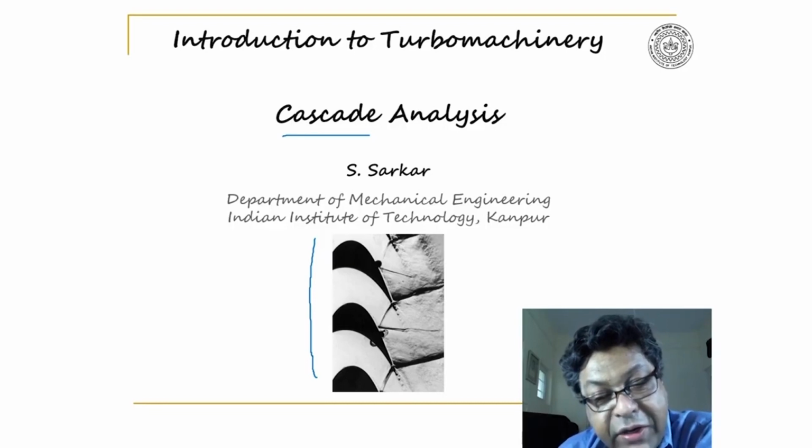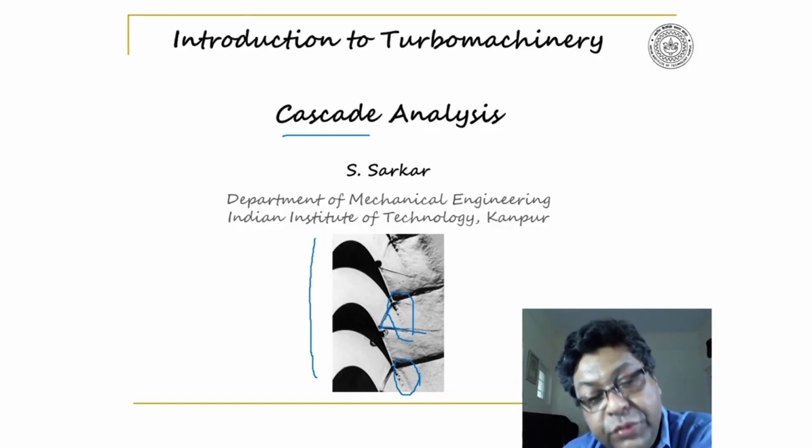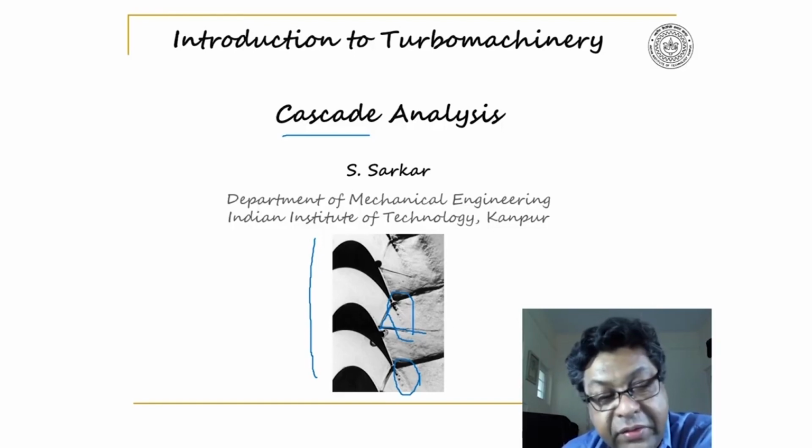and the reflection of shock from the neighboring blade. So here the shock appears and then is reflected, and thereby it interacts with the boundary layer forming on the suction surface. Furthermore, you can appreciate the formation of wake behind the blade. Thus, it has given a fairly good picture of flow through the turbine blade.